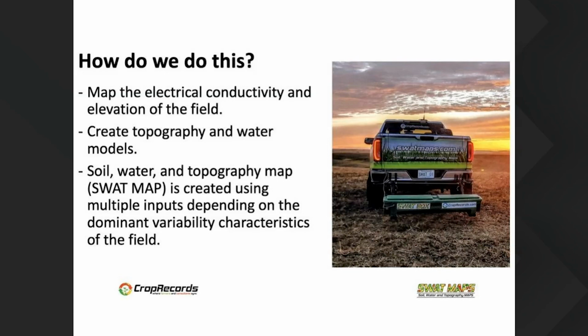But at the end of the day, it's a really good tool for delineating salt gradients and soil texture. We also collect elevation data, very accurate RTK elevations. We either collect it at the time in the field or can get it through LiDAR or other sources. And we create topography and water flow and accumulation models from that, which can also go into the final SWAT map.